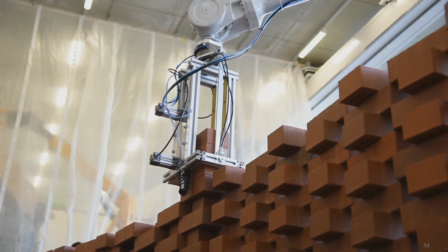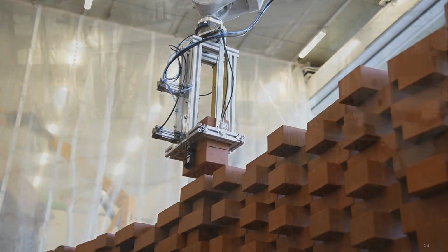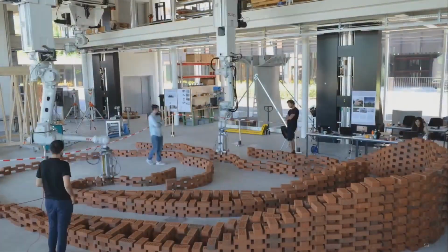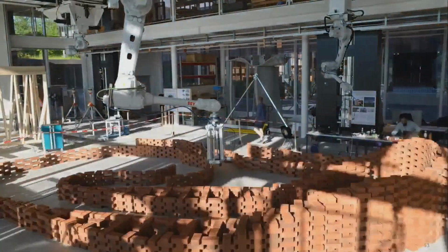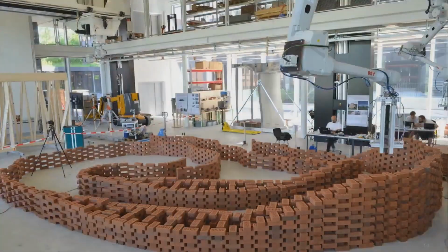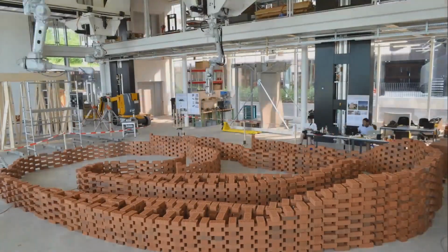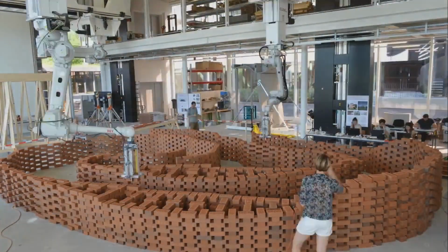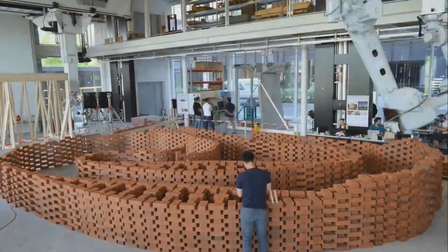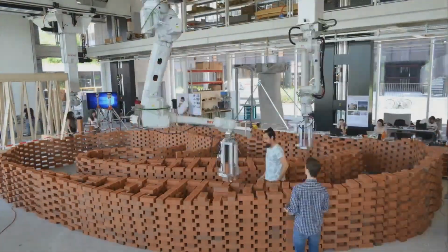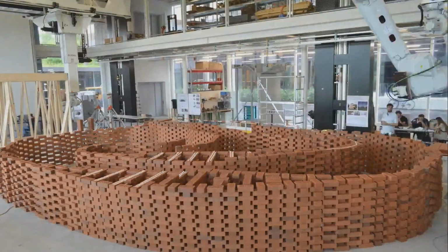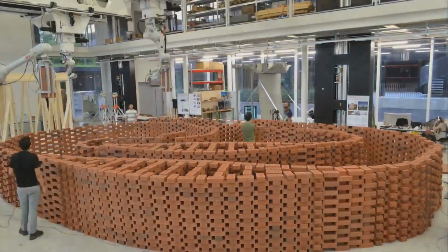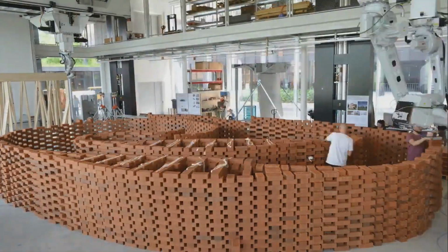One task that was coming together with the sequence was not only how to reach every brick so that the robots don't hit each other, but also so that the robot end effector doesn't reach the neighboring bricks. So we also had to consider the approach direction and which robot could place which brick to make sure that they're all getting there. And then this was built during a time frame of less than 4 weeks. I think 3.5 weeks. We managed to build the whole thing.